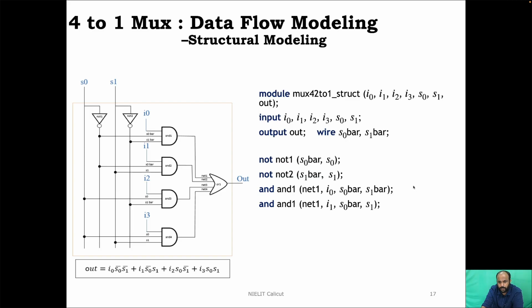So repeat it for the other 3 gates also with different names. Not like this, you can name them AND2, AND3, AND4. I just purposefully kept it because if you write like this, it will give you a multiple instance error. So though you are instantiating the same AND gate, each time you give it a different label. The first AND gate is AND1, the next AND gate must be AND2, the third AND gate should be AND3, the fourth AND gate should be AND4, and so on. So according to what you have labeled in the circuit, let there be a one-to-one correspondence.